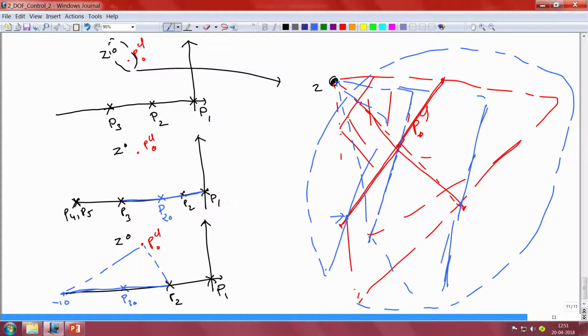In this case we have two poles that are uncertain and the gain that is uncertain, but yet we can systematically determine the location of the zero of the controller from the point PCL naught that restricts the variation of the closed loop pole to within the specified limit. The exact shape of this curve, however, may be more complicated than the one that we considered in the previous examples, and hence one can even take the help of a computer in order to obtain the area within which the closed loop pole will vary when we have each of these parameters of the plant being uncertain.